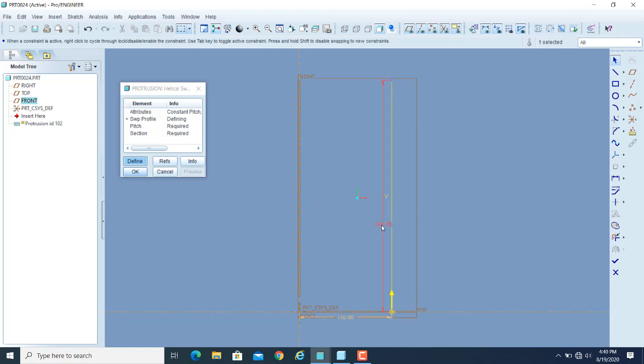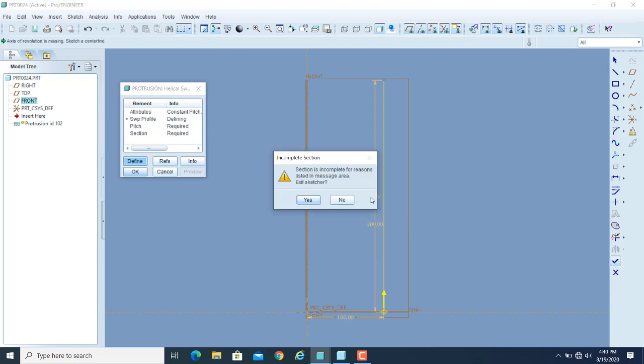And you can set the dimensions of the profile as well, let it be 300. So at this point, now if I click on the check mark button, again it will give you that error, and the error is the axis of revolution. So as I told you that it is a revolve object, so for revolution you must define the axis. So we have not yet defined that.